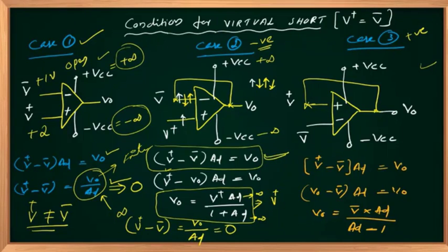So even if you are applying a plus infinity or minus infinity, due to the negative feedback, due to the corrective mechanism in the circuit, the output will be in a particular range. It never goes to infinity. Still, you will be having some doubts. Hold on, that will be cleared after explaining case number 3.